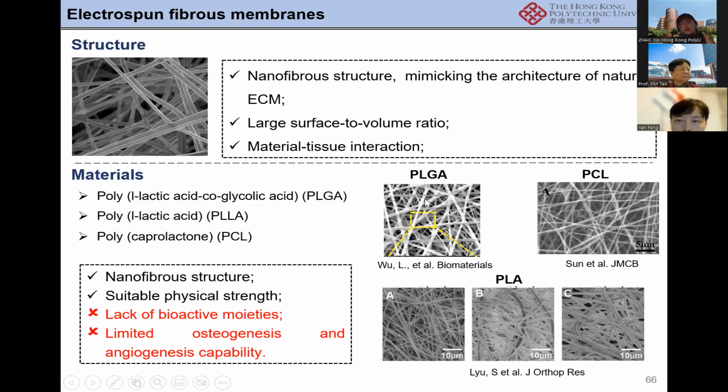Yeah, they become spiral shaped. In this case, we can make the materials elastic. So this is one thing. And the other one is that we can change the way we electrospin the materials. For example, nowadays people also make auxetic structures using electrospun fibers. In this case, by varying the process, we can change the pore shape of the electrospun fibers, and also make the materials elastic.